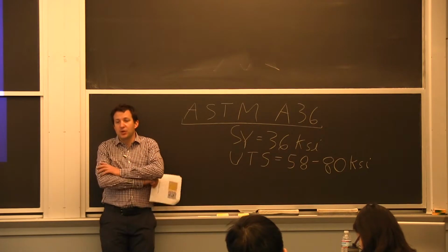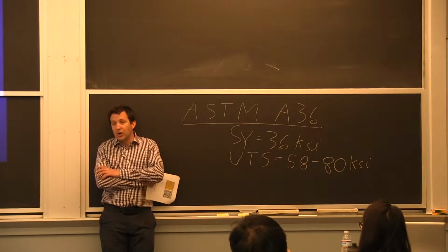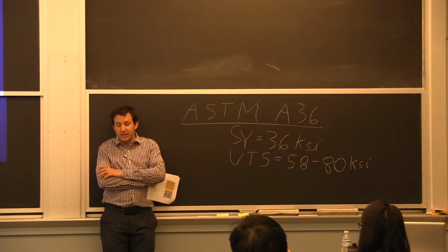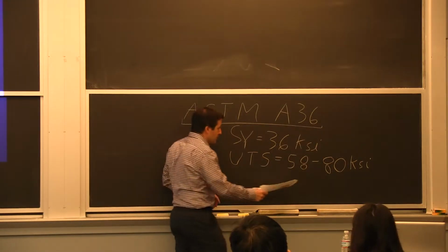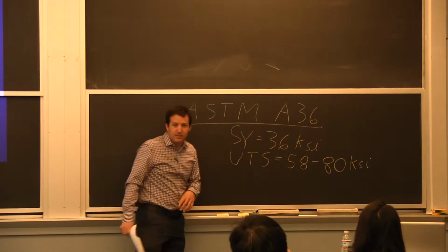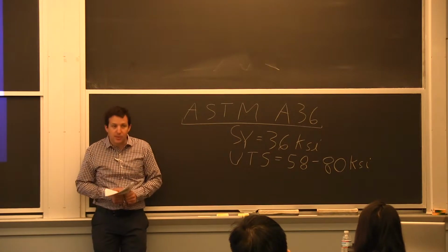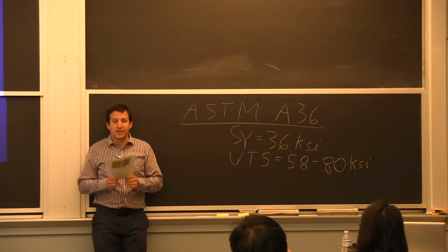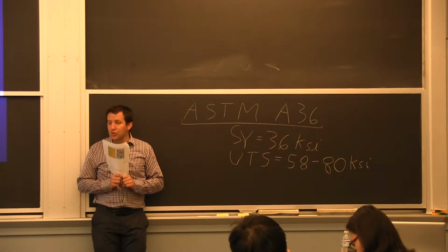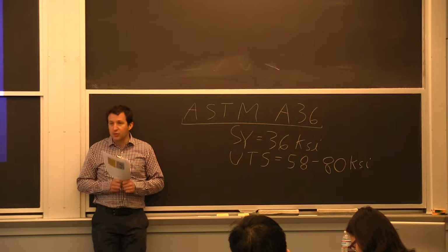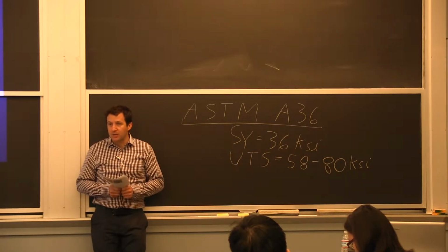There are applications where you want things to deform. Well, if the yield strength is too high, it's not going to be possible to deform it. So, personally, I do like to see that there are some maximums here. A lot of steel specifications also have maximum hardness in these ASTMs. And some of that is to resist hydrogen embrittlement or hydrogen-induced cracking. There are very specific reasons for putting them on.